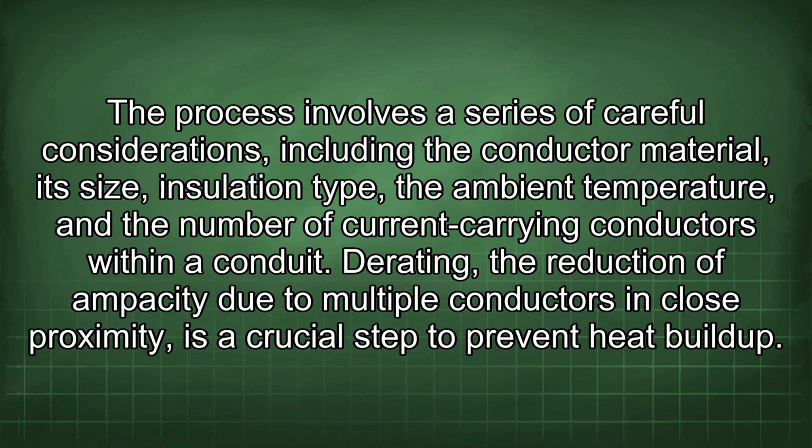The process involves a series of careful considerations, including the conductor material, its size, insulation type, the ambient temperature, and the number of current-carrying conductors within a conduit. Derating, the reduction of ampacity due to multiple conductors in close proximity, is a crucial step to prevent heat buildup.